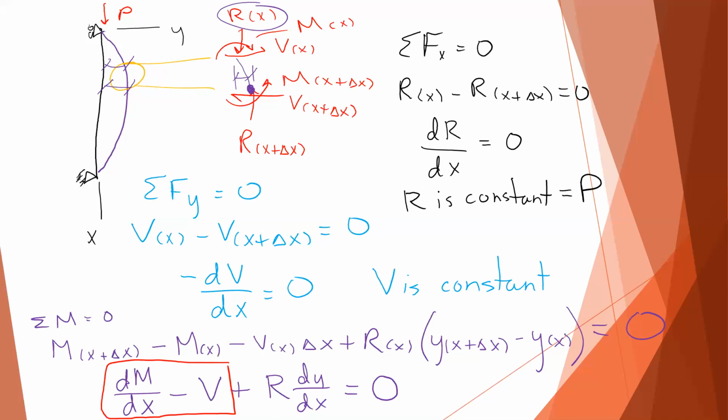The difference is that now we also have this term with an axial load that's offset. Before we didn't have any axial load, we just had bending. Now we have axial load applied, so this last term is a new term that accounts for the axial load. We've previously agreed that R equals P, correct? So we can substitute P in place of R.